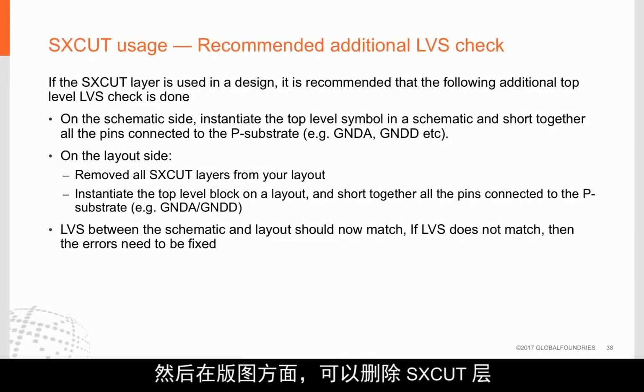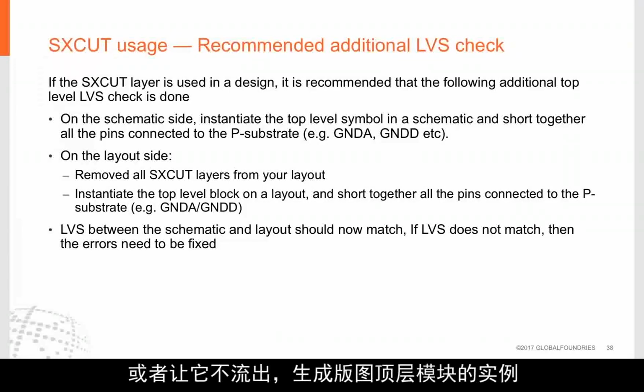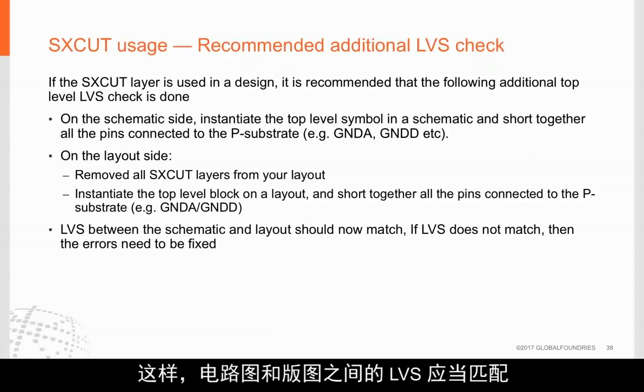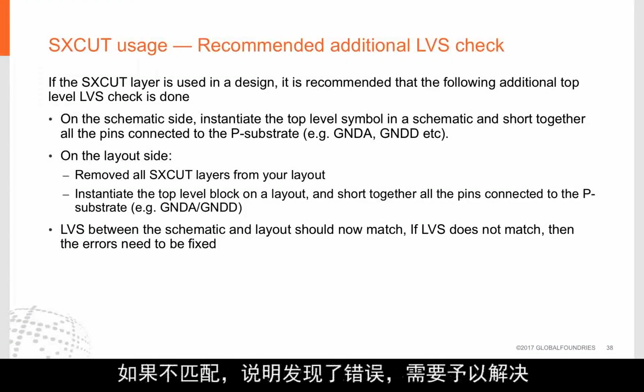And then on the layout side, you can remove the SXCUT layer or simply not stream it out and instantiate the top-level block of the layout and short all the pins together to the P substrate. Then LVS between the schematic and the layout should match. If it doesn't match, then you've found an error and you need to resolve it.